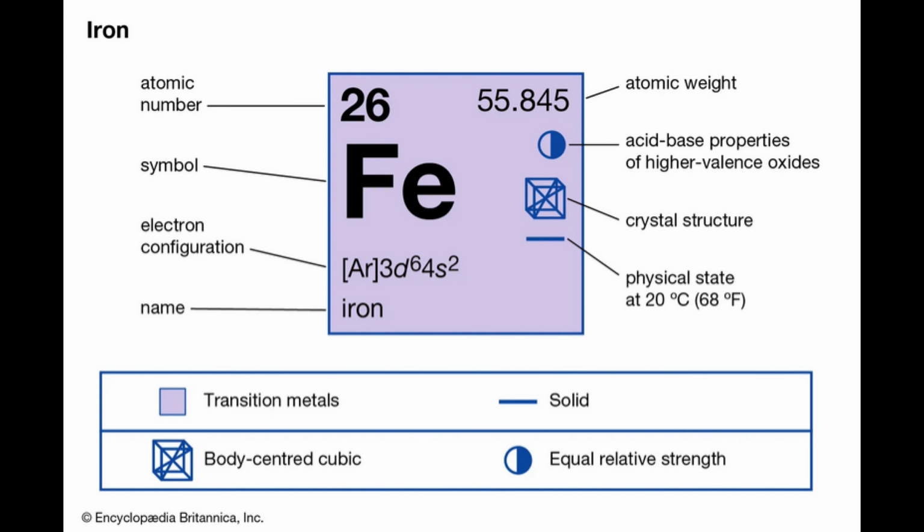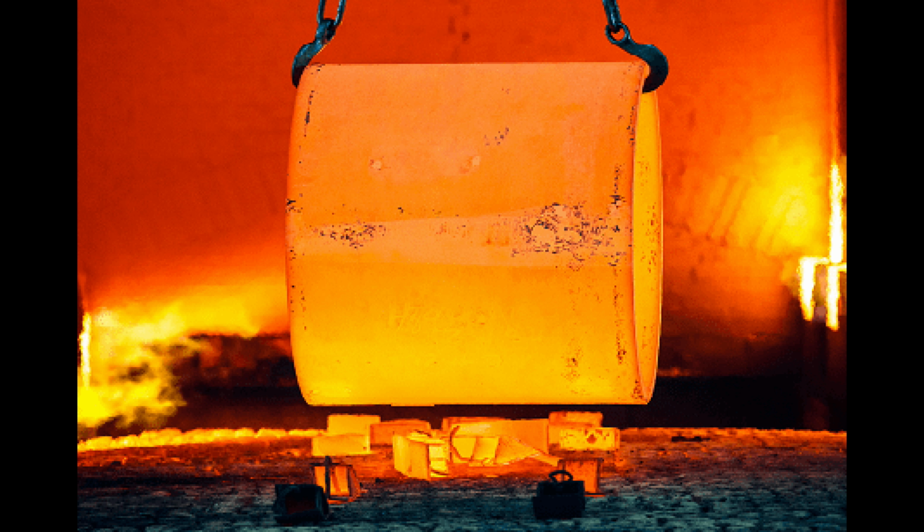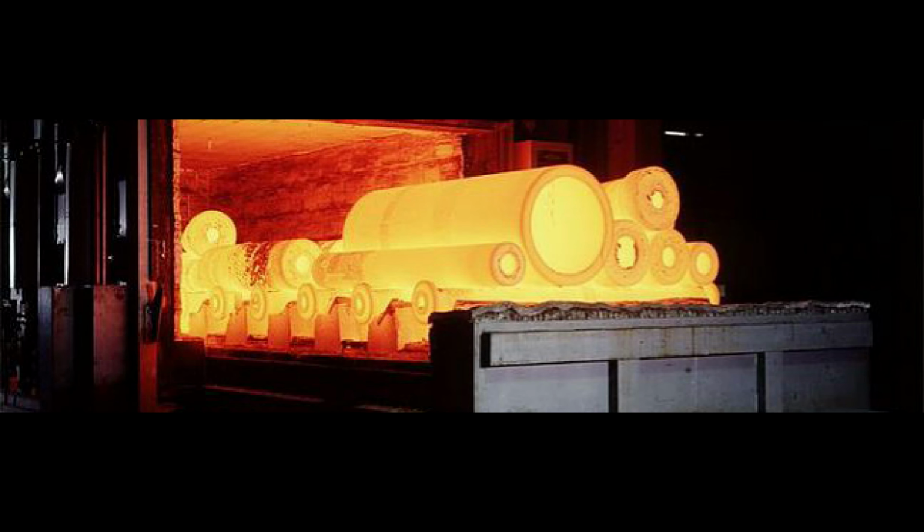The chemical composition, of course, is fundamentally important to determine the properties of a metal. In this case, I guess we're mostly talking about steel, but it pretty much applies across the board. It turns out that there's a process called heat treatment that has a dramatic effect on the properties of steel. And heat treatment is basically defined as the controlled thermal processing of heating and cooling that results in desired improvements in properties.